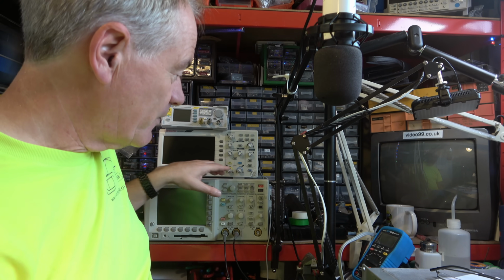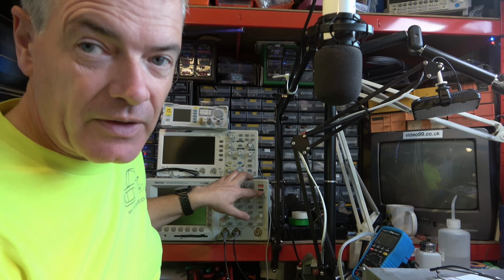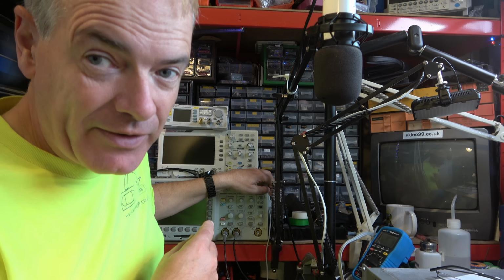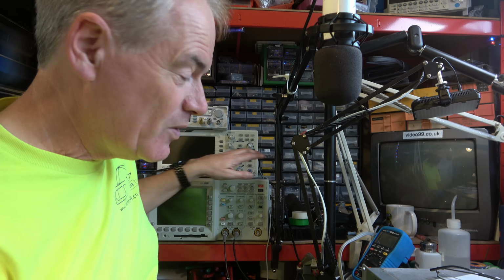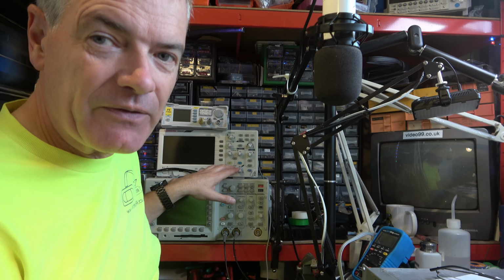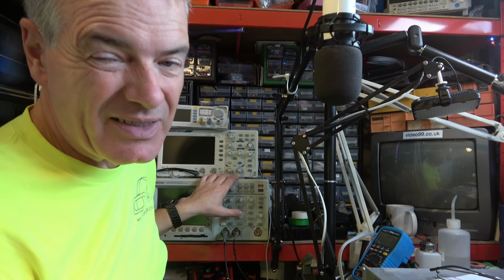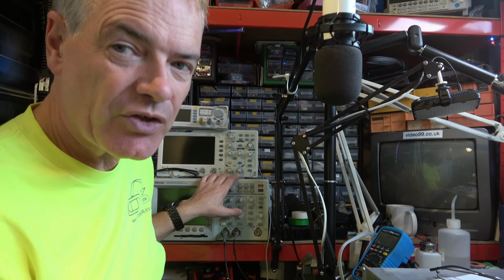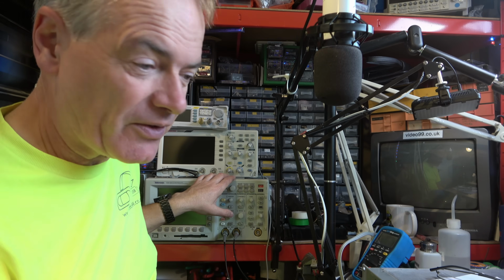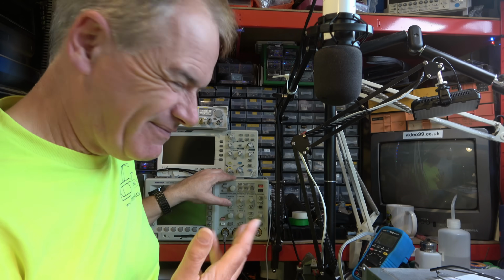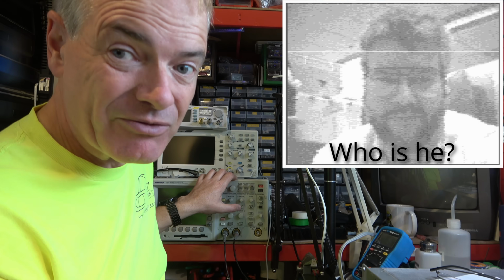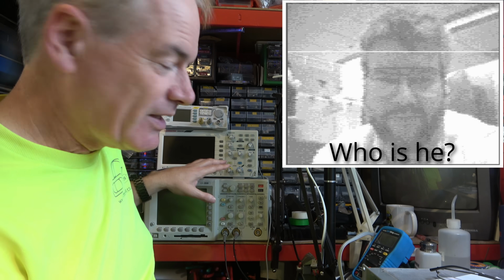And now we've found that with the 3VID module, it enhances triggering functions. You can trigger on a line, but with the new firmware in here, you can do that anyway. So it can turn it into a vectorscope, but it's a little bit limited, and I'm not sure how far I'd trust it. And you can also display the actual image on here, which could be handy if you're working on video, but the image quality wasn't really usable, and even the one that it shows in the manual isn't really usable. So I don't think that's terribly useful.